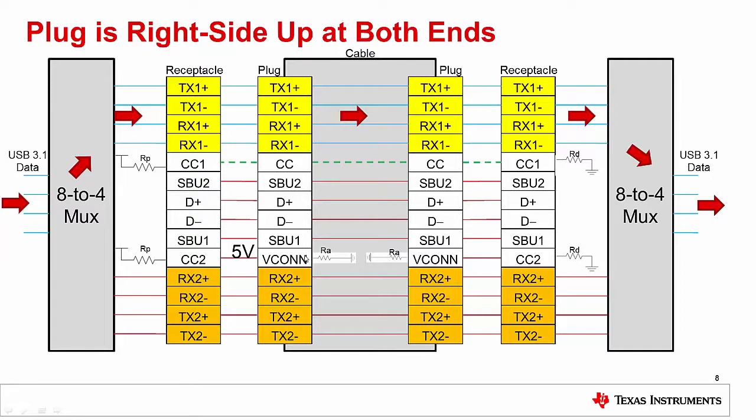So the electronics in the cable can't power from VBus directly because they would have to power from much higher voltage, which makes them more expensive. So instead, the solution that USB came up with is to require the host that's using the superspeed lanes to provide a 5 volt supply. That way you can still have low voltage electronics in the cable that are powered.